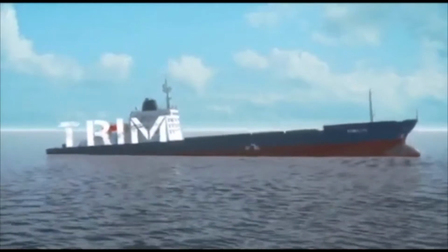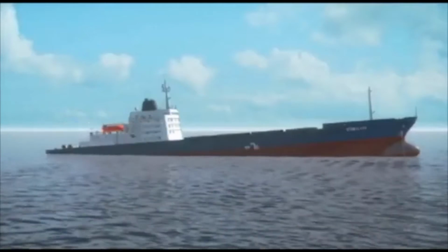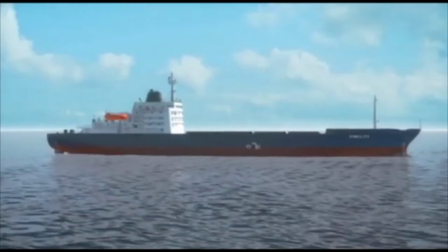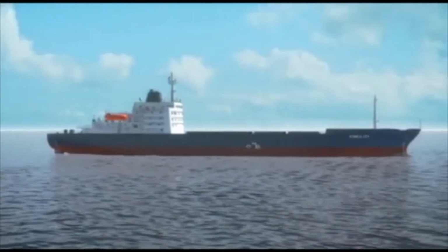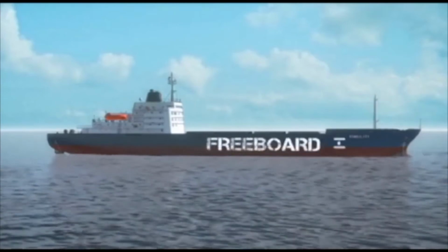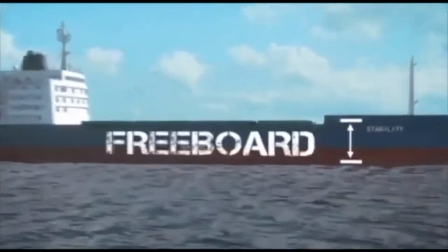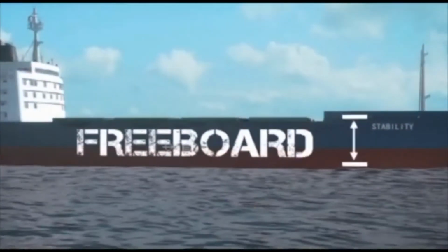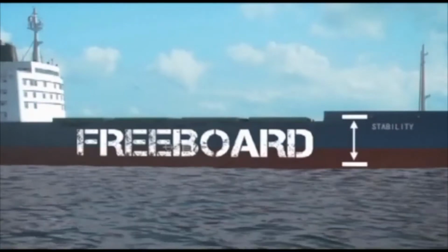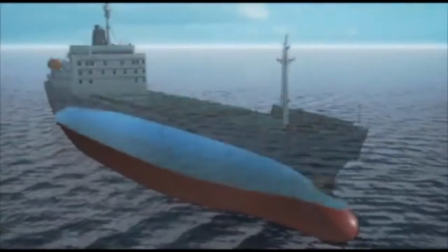Trim is the difference in draft, forward and aft. The trim of a vessel can be found by reading the draft marks on its hull. These draft marks are placed as close to the perpendiculars as the shape of the hull allows. A vessel's freeboard is the vertical distance between the waterline and the highest watertight deck of the hull, usually the main deck. Freeboard is important because it is part of what determines the volume of the space above the waterline.